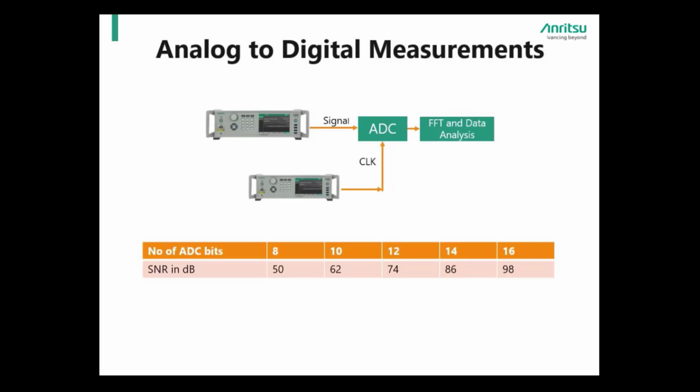an ADC. It is important to also note that the signal generator used as the input RF signal should have very good phase noise and harmonic performance, as this will contribute to ENOB measurement accuracy. The signal generator used as a clock source must also have good phase noise, especially in the pedestal region above 10 kHz offset from the carrier.